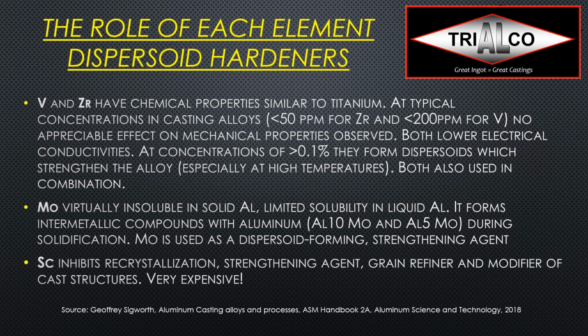Another one would be scandium, and that would have a lot of other very nice side effects. It inhibits recrystallization, it's strengthening, it's a grain refiner at the same time, and a modifier. The only downside is it's ridiculously expensive. So you really want to stay away from that one unless money is really not an object.